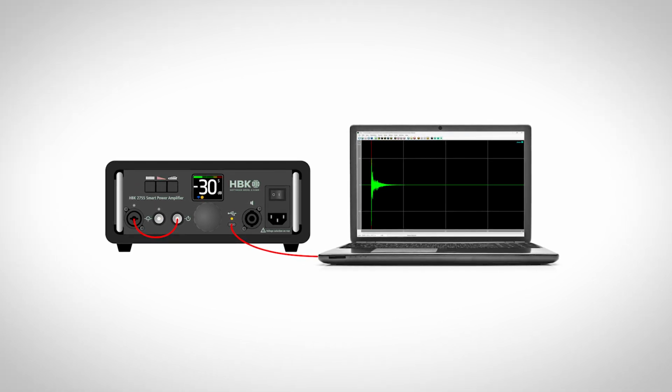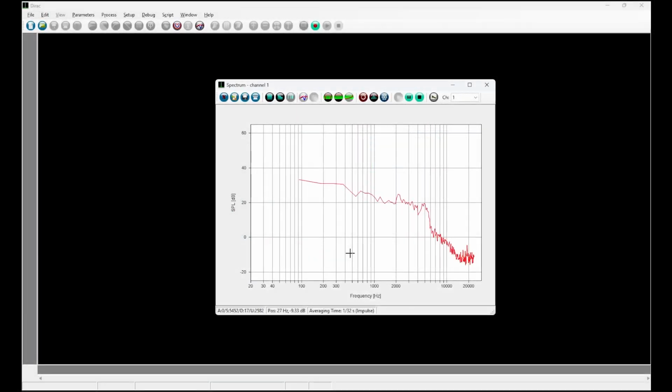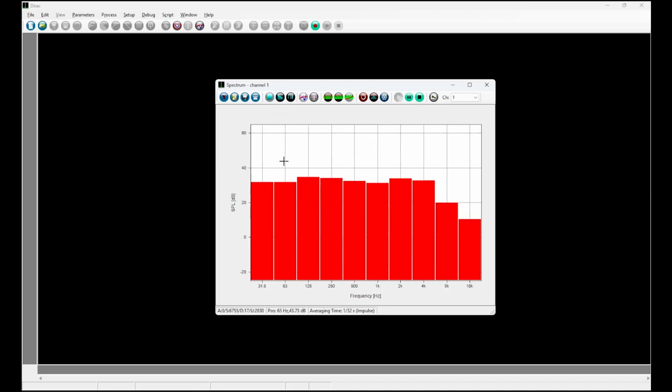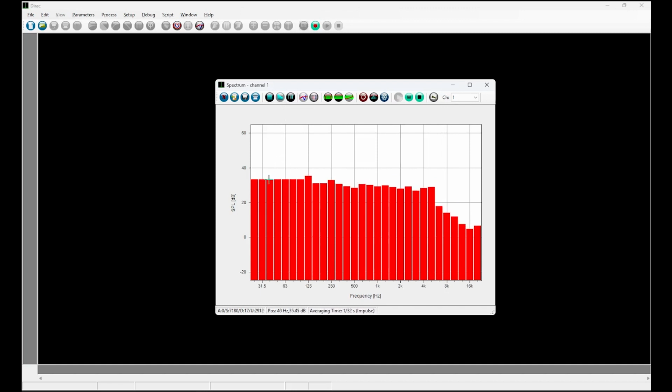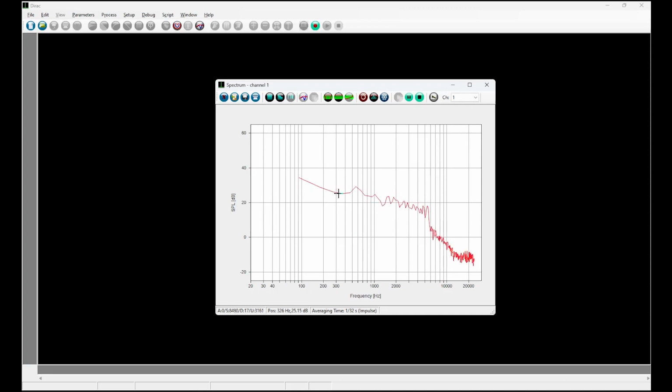band-limited noise signal. At the current minimum FFT size, the frequency step size is as high as 94 Hz, which is easily visible in a continuous spectrum starting at the same 94 Hz, while in the band spectra such a large step size covers multiple lower bands, which are therefore obviously not accurate at this minimum FFT size. While increasing the FFT size, so do the minimum averaging time and accuracy of the spectrum, in particular at low frequencies, as will be shown now.